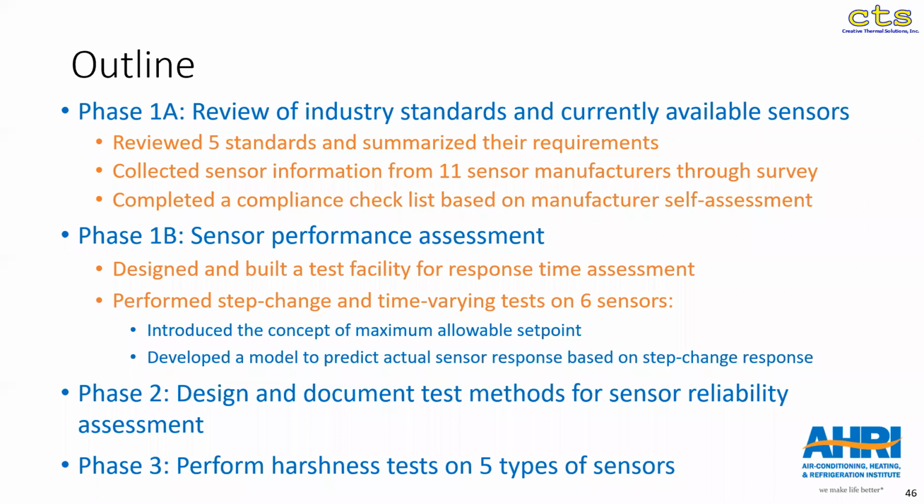Yeah, thank you. Phase 1B was concerned with mostly what Phil just described with the time-varying concentrations and how the sensor responses can be derived from simple step changes. So this has to do, of course, with the fact that most concentration changes in real life, in real leak scenarios, are never ideal step changes. And I'll talk about that a little bit. We will introduce here the concept of the maximum allowable set point, which goes nicely along what Phil just explained to us, and then show you how we can actually derive these actual sensor responses for the time varying concentrations.